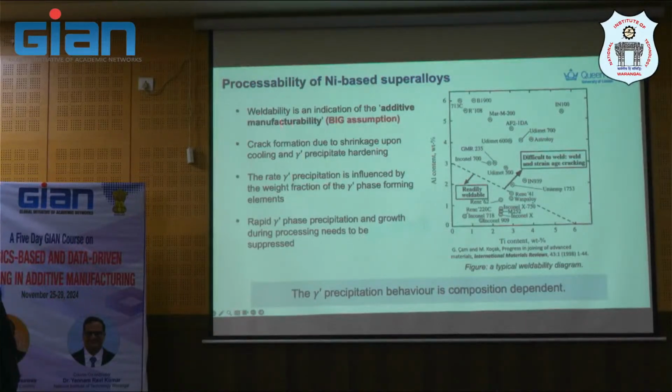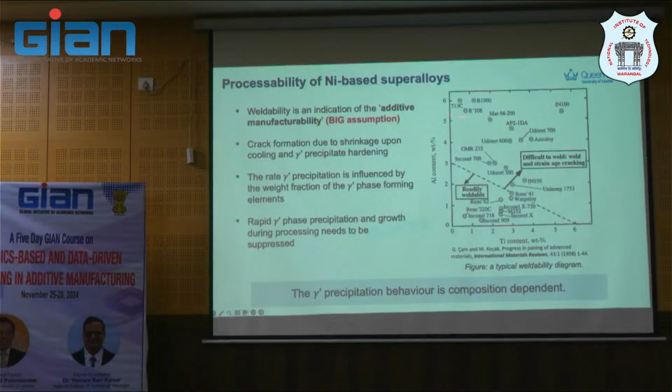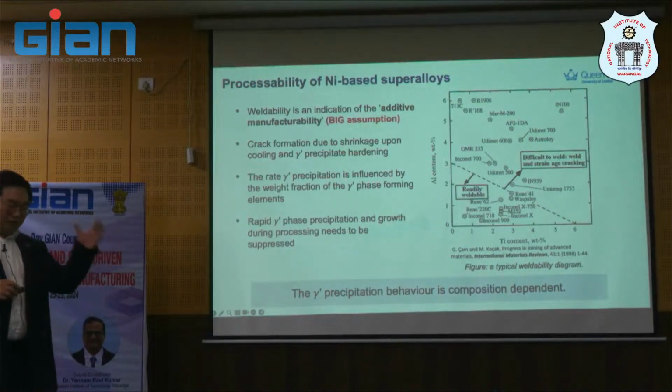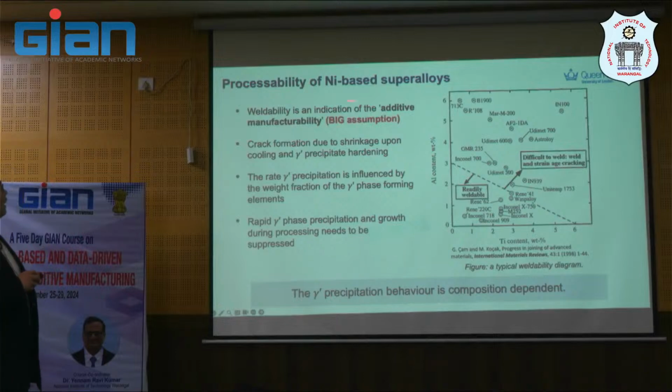So that's how I said yesterday about the Inconel 718. So we start from what we have, and then based on what we have, we believe in the weldability diagram, but we know that it doesn't have anything doing with the additive manufacturing. But we borrow this concept and we assume that this additive manufacturability actually similar, I would say, to weldability, and this is a big assumption. That's why we follow this kind of diagram to develop some indices for the crack.